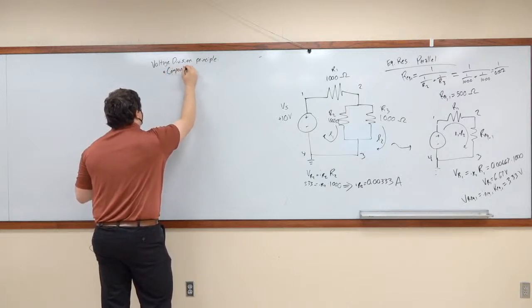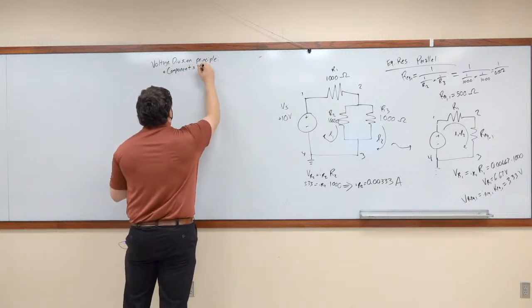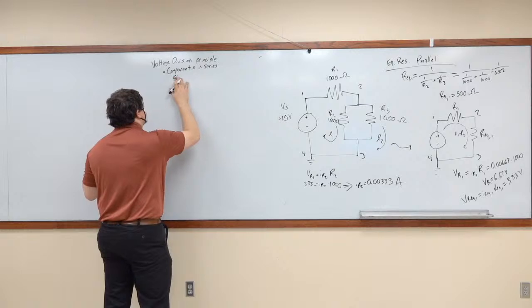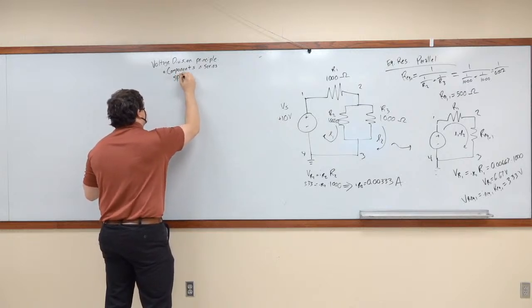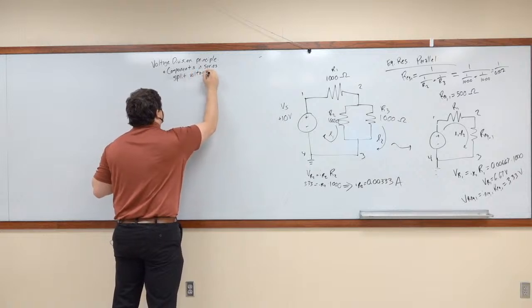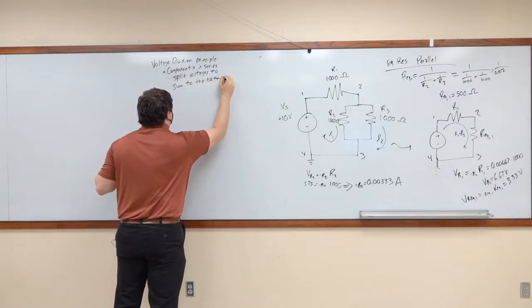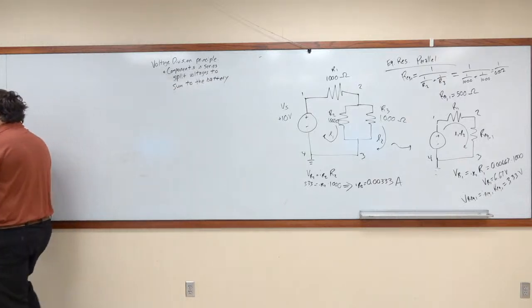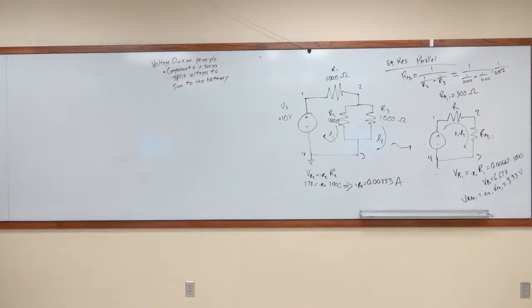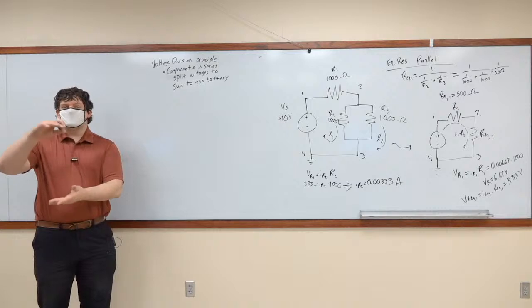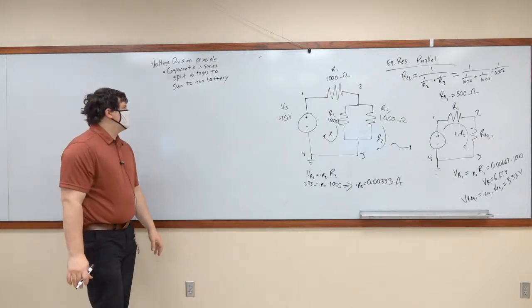Components, I was going to write resistances, but this is true for any components. In series, they split, well, no, not share, dang, split. So if you have resistances that are all in series connected to a battery, then quite frankly, all of those resistors are going to share voltages, and they're all going to sum to whatever the voltage is applied across both ends.